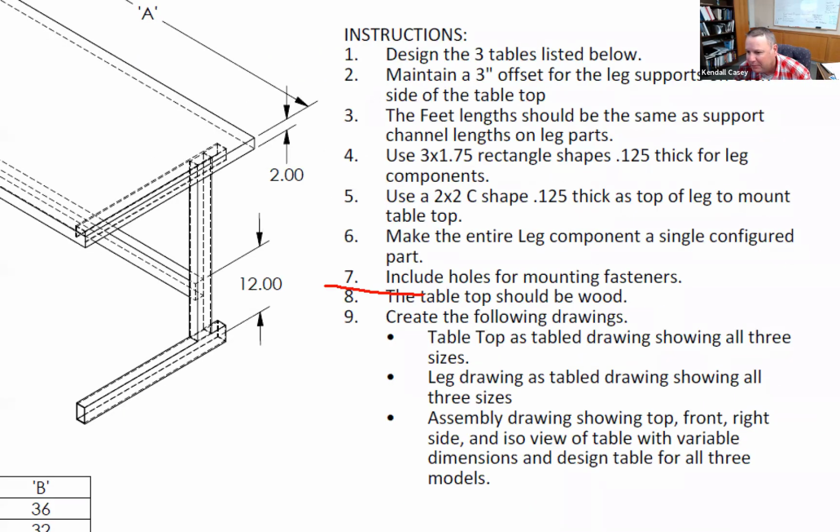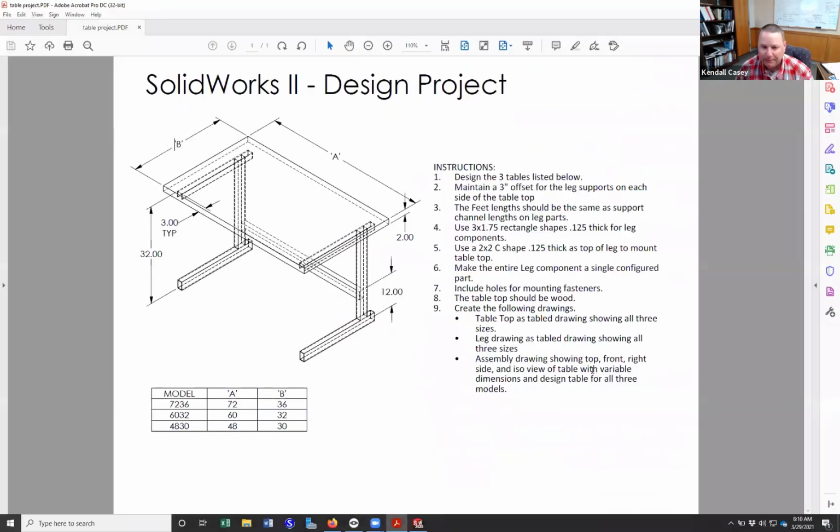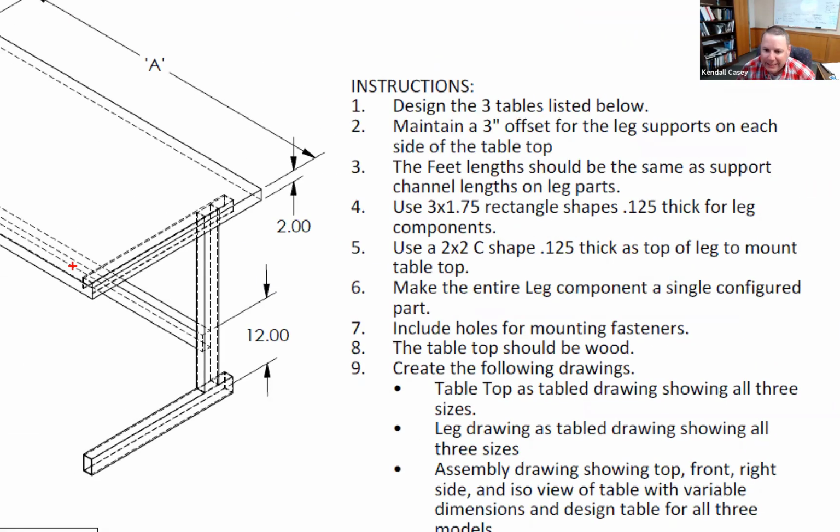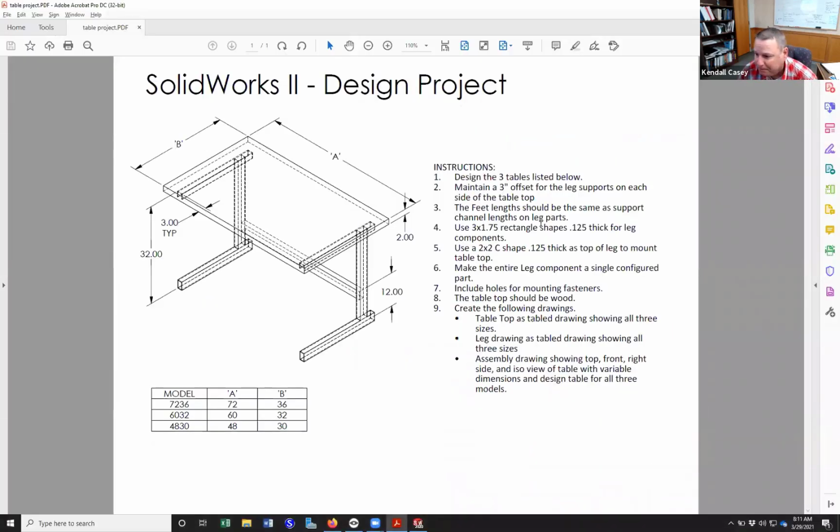Okay, so I guess we do have to put some holes and use some fasteners in there, and I know we've got some trouble with some fastener components, but I will include some wood screws or something that will come up from the bottom. I'll put those in the assignment and just poke holes for that. So you'd need to put at least 2 holes on each end, maybe 3, on the C channel. And I don't think there's any point in pre-drilling those into the wood. We would just screw those into the wood. If you felt like pre-drilling them into the wood, that'd be okay too.